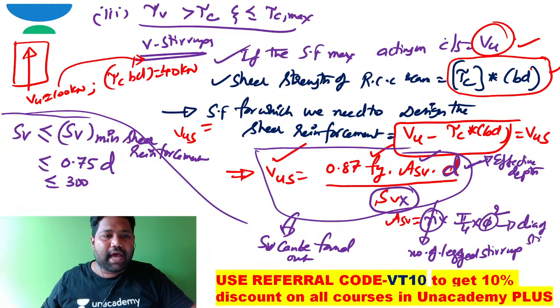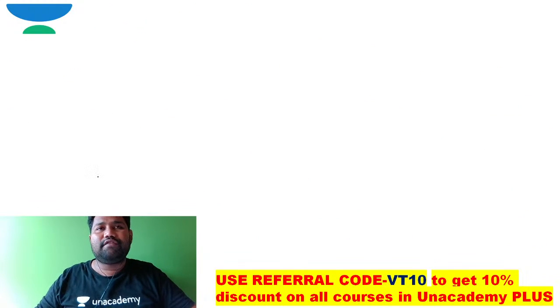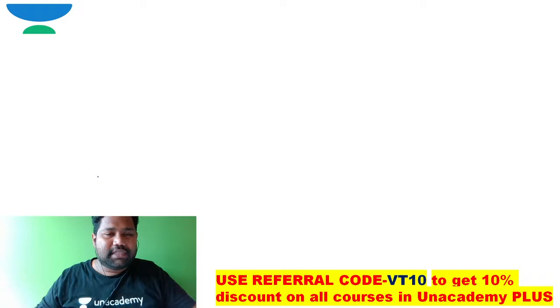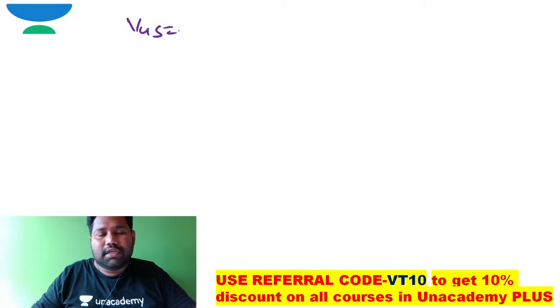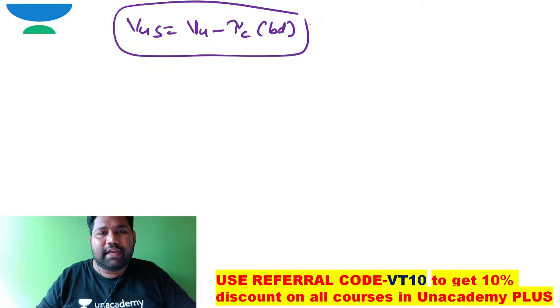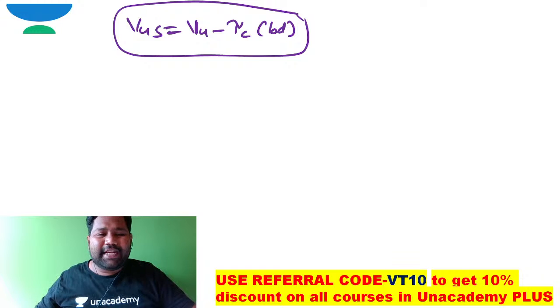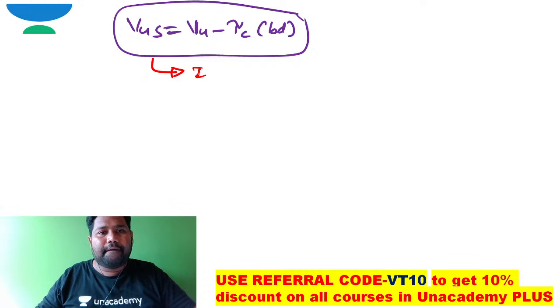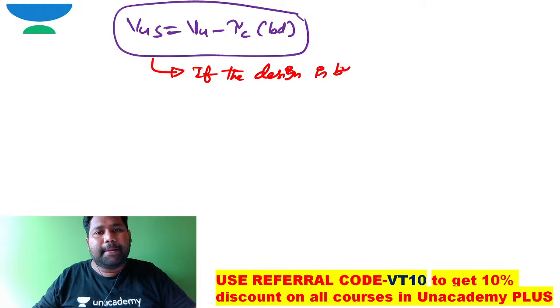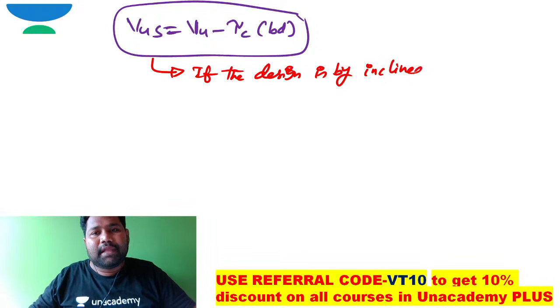Some people will say, sir, in your previous slide you mentioned that you can design the shear reinforcement by vertical stirrups or by inclined stirrups. Sir, for the same thing, Vus is equal to VU minus tau c times bd, this is fine, right? Now I want to design the shear reinforcement using inclined stirrups. If the design is by inclined stirrups,